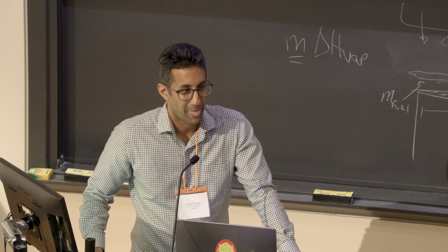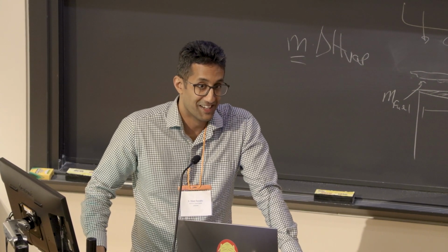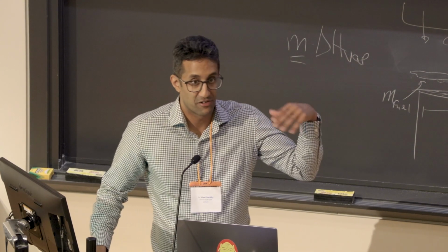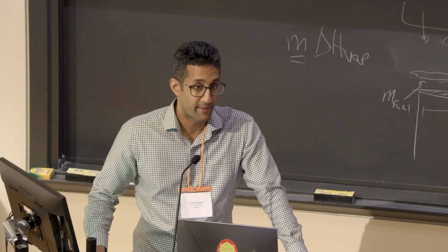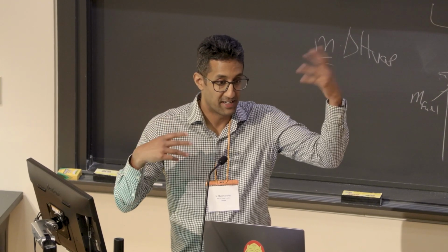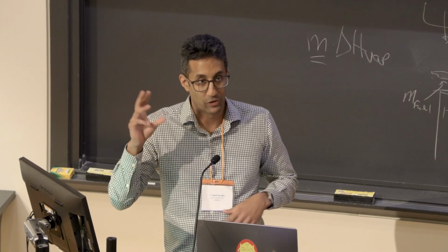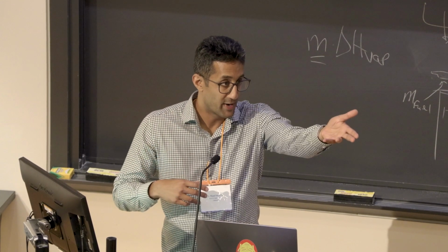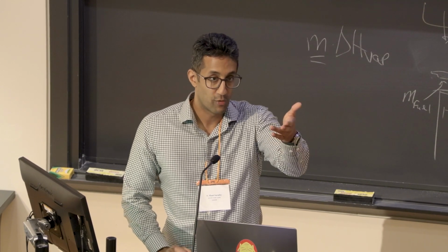I work a lot with CFD modelers. You've got to provide them kinetics which they want, which are compact. You lose a lot of the fundamental aspects, you lose a lot of the theory, but again, it's a matter of what they want to predict. I come at it from both ways, right? I think fluid mechanics is important, chemistry is important. A DNS simulation is very detailed in the fluid mechanics aspects, very crude in the kinetics aspects, and somewhere you come in the middle. I think reactor networks with detailed chemistry, like I showed, with flow reactors, can help you in many cases.